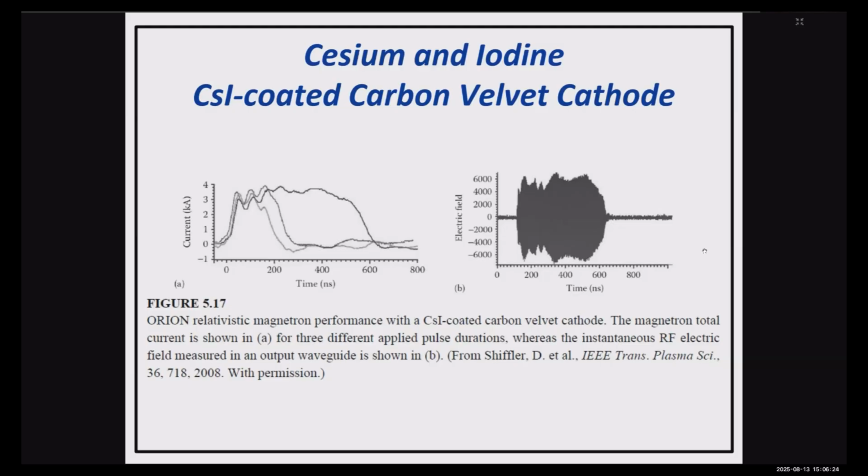It will be trapped in this region, like a magnetic mirror. So you're trying to have a magnetic field at the cathode that is different from the magnetic field in the interaction region, a stronger magnetic field at the cathode. Is that correct? Yes. Then it will create a magnetic mirror.